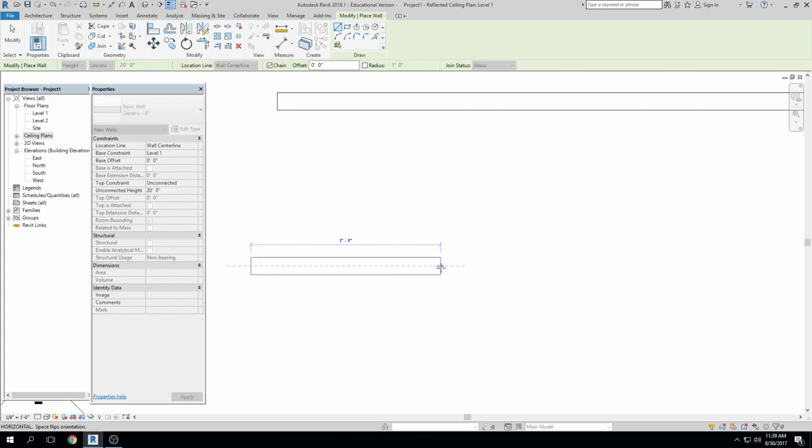Sometimes they go from center to center, or they try and draw from another source as if you were trying to do a from command, like 3 feet from this wall, I want to draw this object, right? So you just have to keep your eye on the temporary dimensions, okay? But what's nice about them is that once I've drawn an object, it kind of tells me how big it is, right?